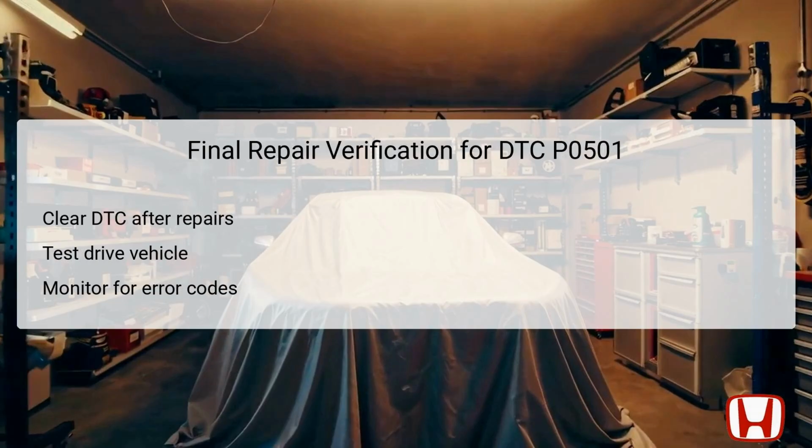After performing the necessary repairs for DTC P0501, it is crucial to clear the DTC from the vehicle's memory using a diagnostic scanner. This step resets the system, allowing the TCM to relearn the new conditions of the repaired components. Following that, take the vehicle for a test drive to verify that all repairs were effective and that the vehicle operates smoothly without any warning lights being triggered.